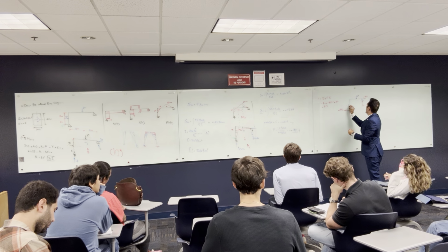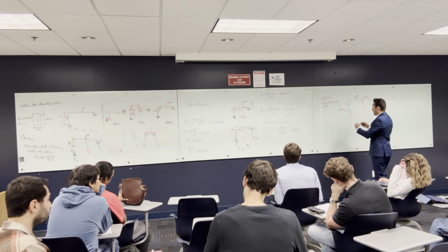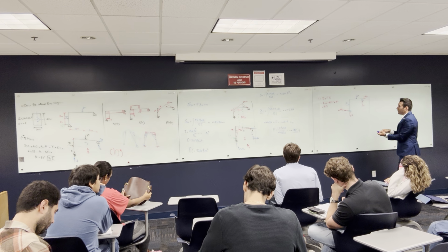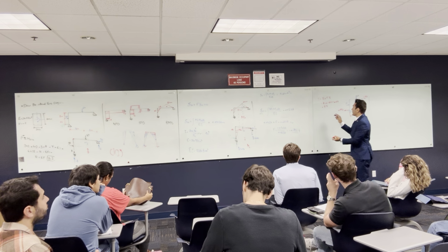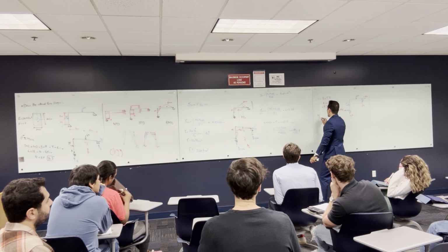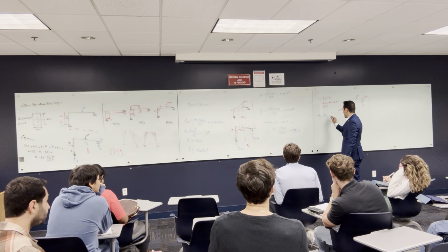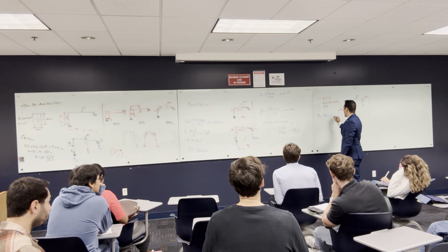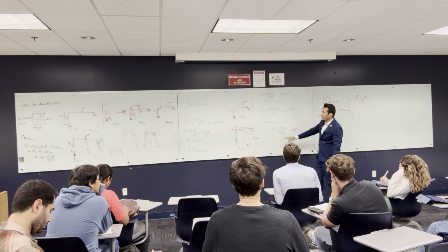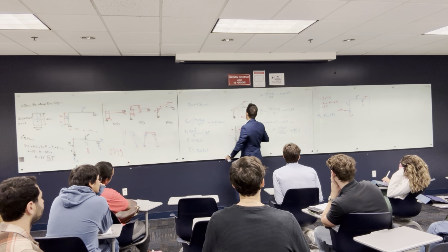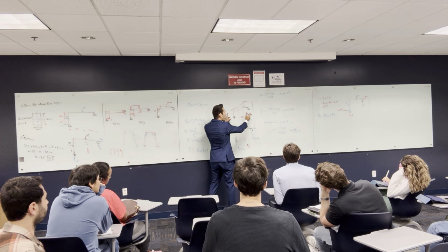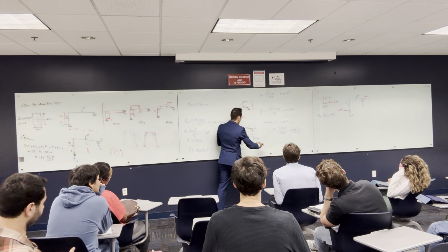6 ton and 3 ton. You can find the bending moment, shear, normal for this, or you can use this equation. The moment at any cross section, M final, is going to be equal to the M that comes from the original load plus F multiplied by M1. So you have this moment and this moment. So the final moment is this plus F multiplied by this.